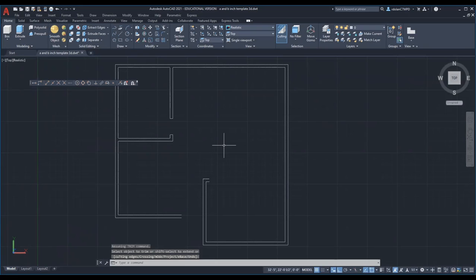Now what you're going to do is on page 1-15, you're going to complete the drawing using the polyline command, and using the offset and the trim and erase. Okay, so you're going to do that. All right, so we'll meet you back here in a little while.